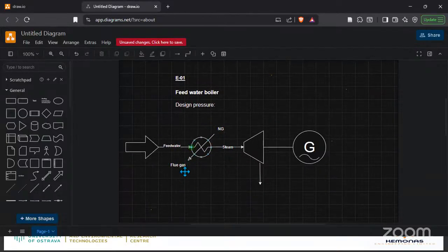This should tell you that we have some energy here that we can recover. We can recover heat from here. Because when you burn the natural gas, it's going to be hot, and it's going to convert this to steam. But also the flue gas is going to be hot. So we can recover heat from this, and also use it to preheat the feed. So now this should open your mind more on how to optimize this facility.